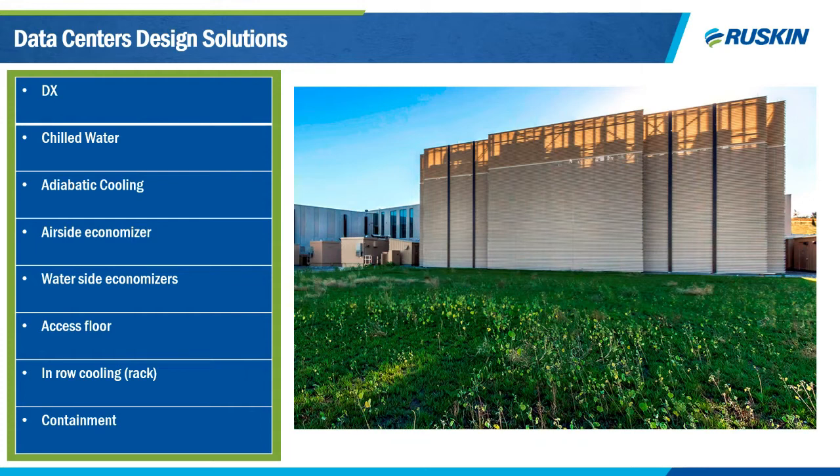So this could be chilled water, this could be DX, this could be adiabatic cooling. That's very popular. We use evaporative cooling to adjust your dry bulb temperature. This could be an air side economizer, and that's where you disable your mechanical cooling and you bring in 100% outside air, and then use basically those ambient conditions to condition and cool the servers.